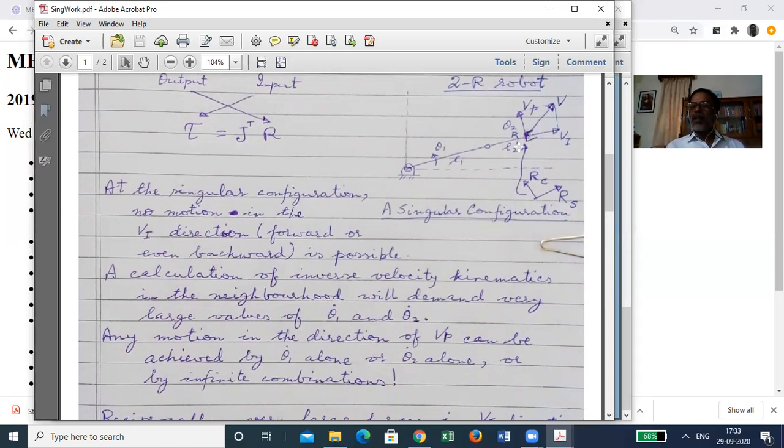at some directions, the manipulator becomes very rigid, and that we know that you have noticed, because against an adversary who is trying to break into your door, if you have to sustain the door with your arms only, what you do? You stretch your arms and put the elbow straight, so that you get a 0-degree angle here, and you put your entire arm at a singular configuration, so that at the joints you do not have to give effort, muscle effort.